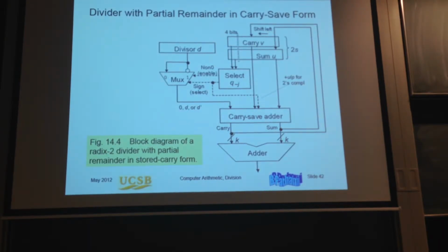And this is the structure of my divider now. It's very much similar. That I am doing normal division, normal iterations. Now I'm keeping the partial remainder in 2 registers. I'm inspecting from these registers 4 bits each iteration. Based on this inspection, I can report them as they are, and here I have a lookup table, or I do the addition and then I implement something. Doesn't matter how I do it here, I'll have some delay.